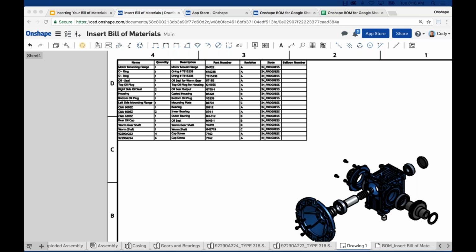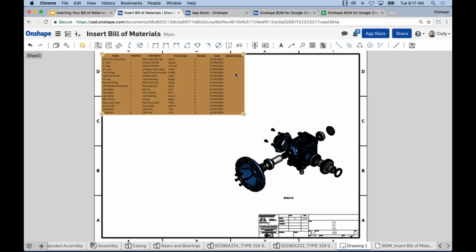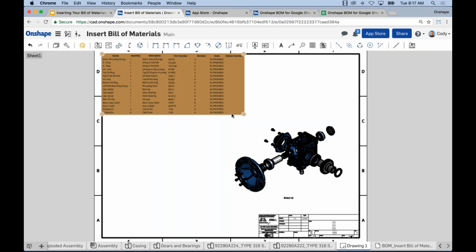I could be wrong. Can find numbers be added and placed on the field of the drawing pointing to items? Find numbers, forgive me. So if you're referring to ballooning the parts and pointing to the right items in the exploded view, which is, I'm assuming, what you're referring to, it's not an automatic thing yet. And that's one thing that we're very aware of. Of course, the next step in the process after you've inserted your bill of materials is to then come in and balloon the parts to match. As of today, they're not parametrically linked. So just keep in mind the ballooning process. I can come in and add a balloon number to OpenBOM and then balloon accordingly, or balloon first and then make sure the balloon numbers match. But as of today, they're not parametrically linked. And that is something that we're working on.